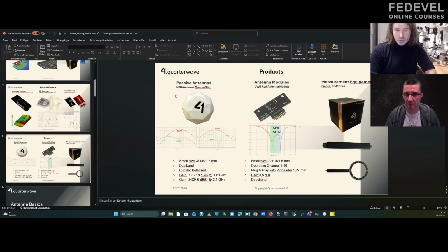The link budget is poor, so you need a high gain, and you also need a circular polarized antenna. Most antennas that you find are linear polarized, and you need circular polarization. Otherwise, you lose an additional 3 dB. And this antenna covers both frequencies, the L and the S band, and is also circular polarized.